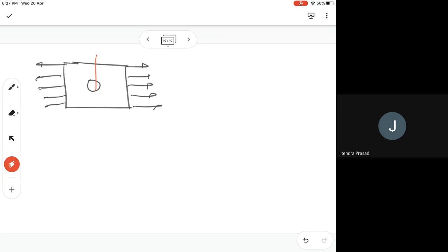Because the total load here is carried over the whole length, but here you have a lower length. So there will be high concentration here, right? And at this point it will be much larger, more than the average basically. So the stresses are high, which really means that if you want an accurate result, you have to design the meshing accordingly.